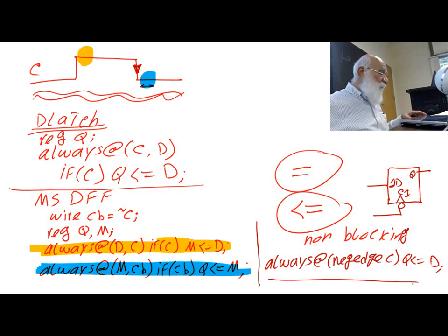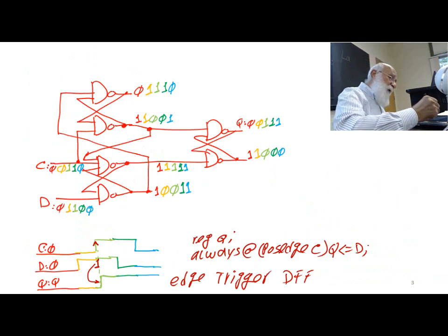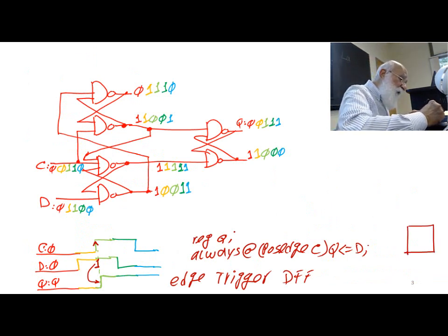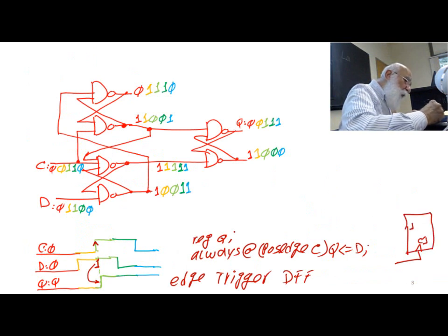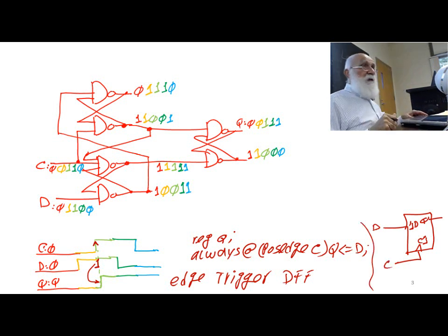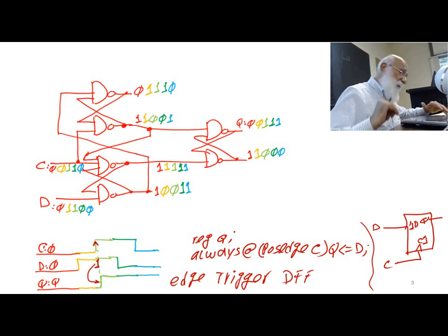And therefore, going to this one, the symbol for this is C1, D, Q. And then again, I'm showing that my D input depends on the clock input, but then with the clock, I'm showing that triangle, meaning the rising edge. If I put a bubble next to the triangle, then it's a falling edge. Okay?